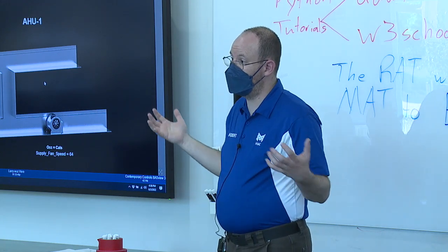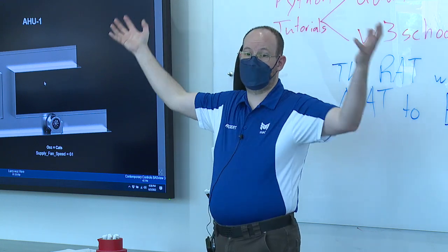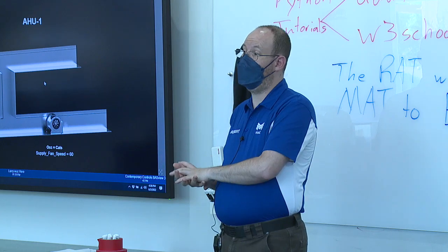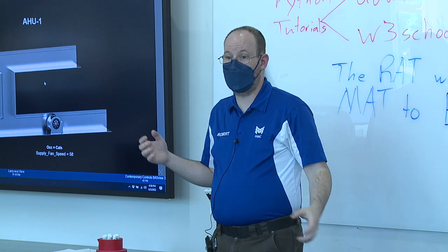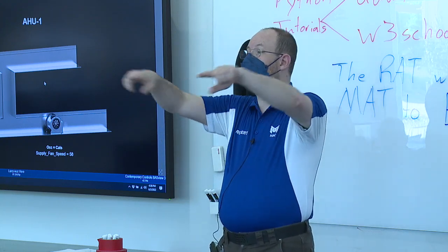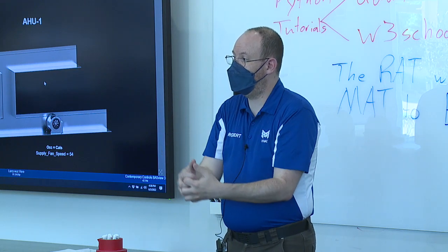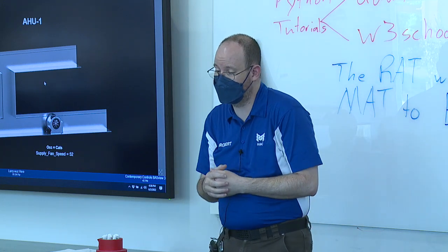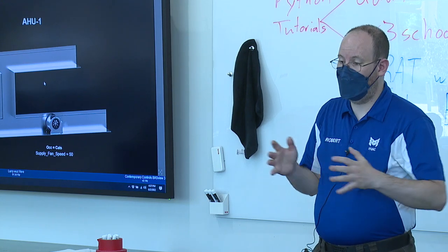In a Niagara system, for example, we've got 60 or so VAV boxes in this building. They're all linked back to one graphic file. So if you do something like add radiant heat to a room, and you add it onto that graphic file, suddenly you've got radiant heat in all the rooms, whether it exists or not. Been there, done that.